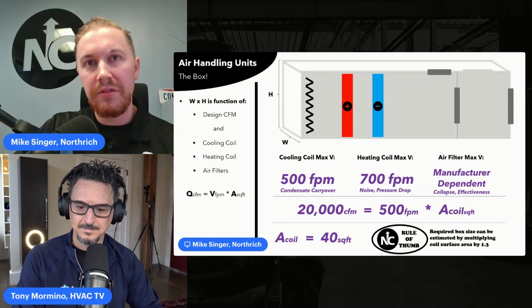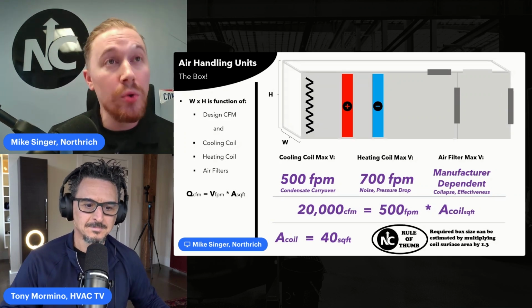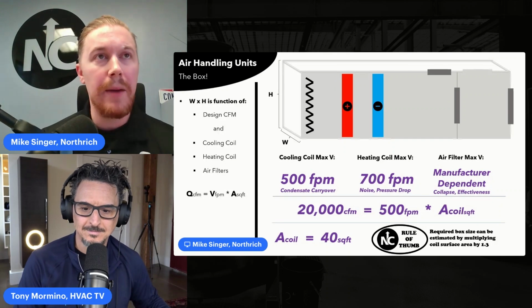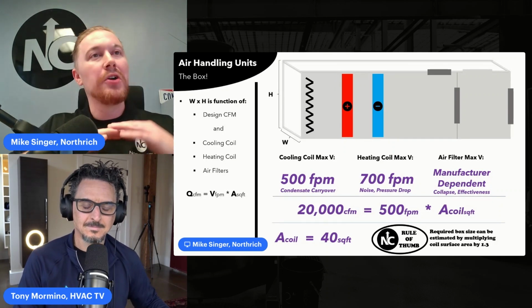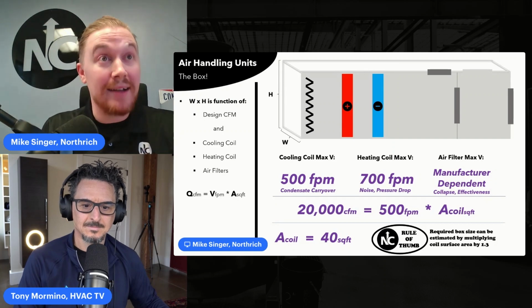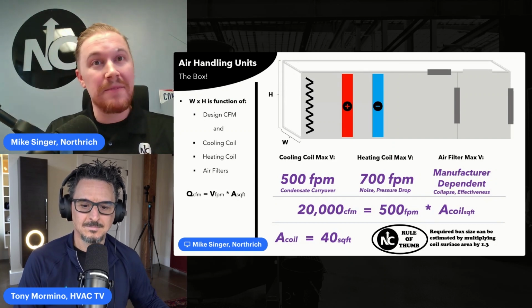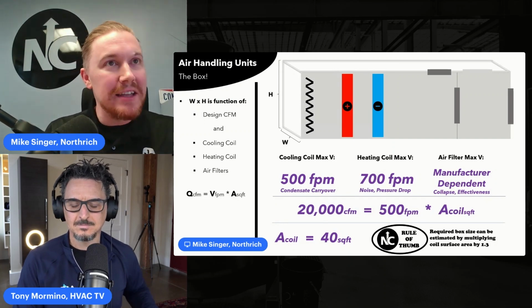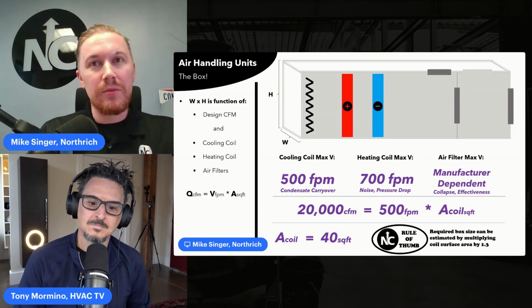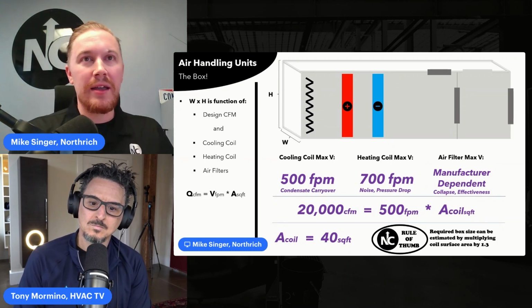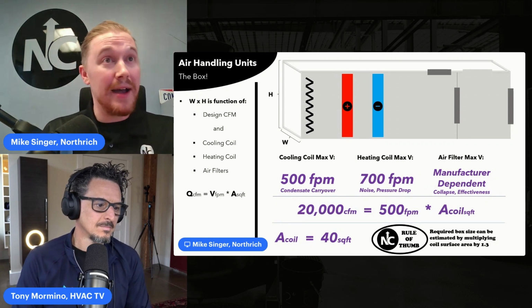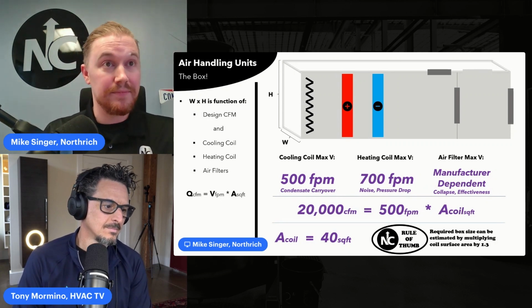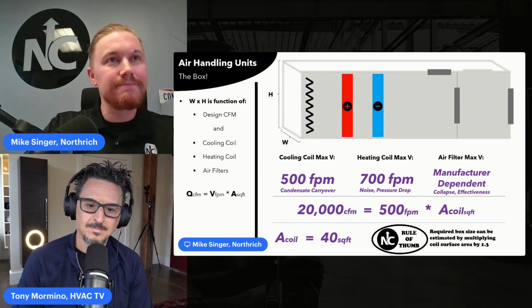And a quick rule of thumb, if you take that cooling coil surface area, multiply it by 1.3, now we're talking about the total cross-sectional area of the box, the actual box size. So if I were to output 50 square feet, when I multiply it by 1.3, I could understand that maybe we have a 5x10 or a 7x7 box size. Okay, that would be acceptable.